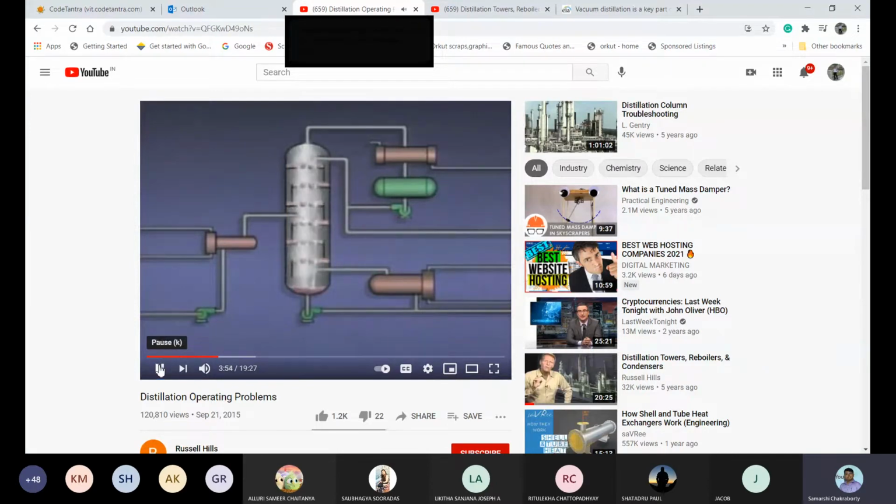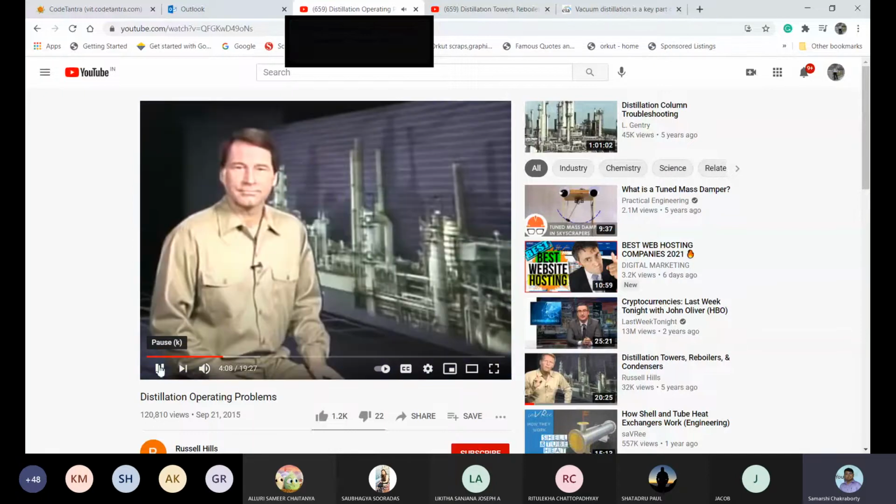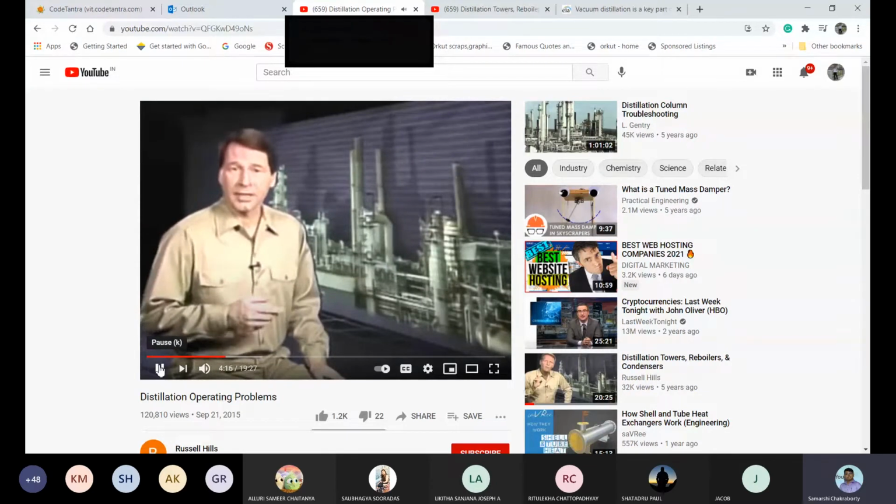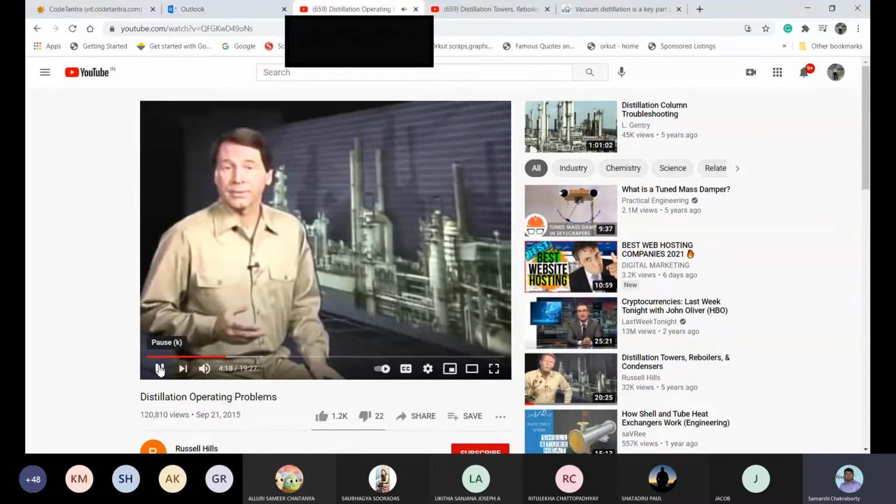Pressure is relieved, liquid flows back down the column, and the pressure buildup begins again. The surging of liquid up and down a column can sometimes damage internal structures of the column. Besides the causes we've described, overloading and flooding can also occur when vapor and liquid flows become restricted by scale buildup or damage to bubble caps or packing.